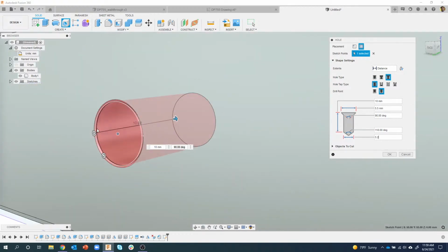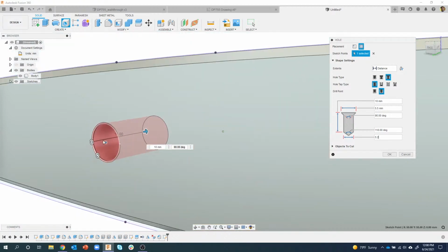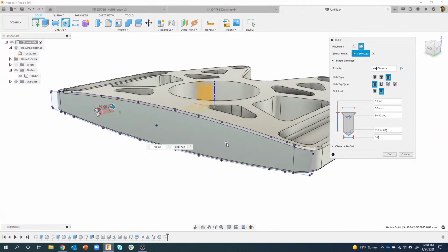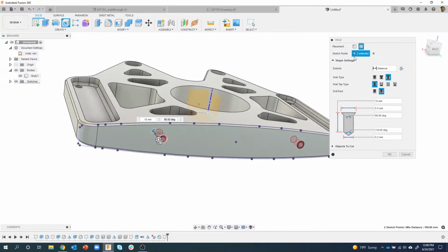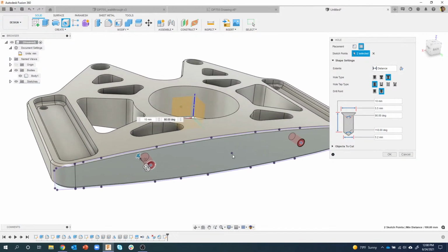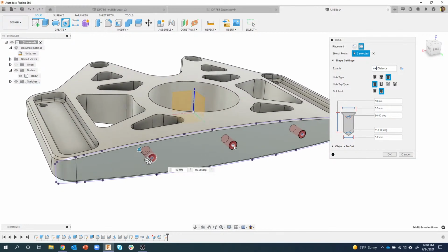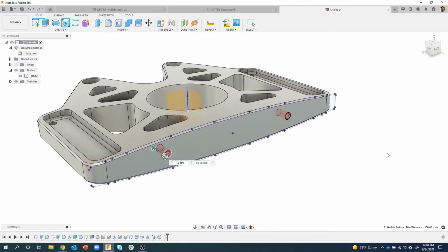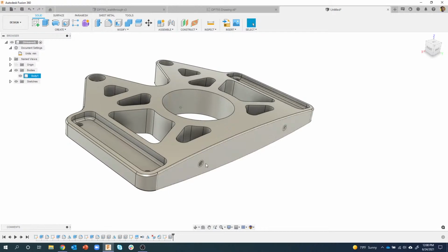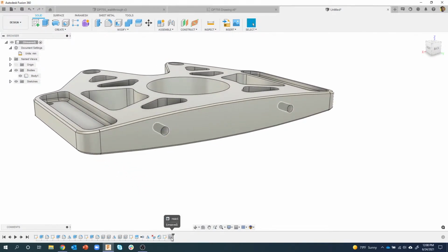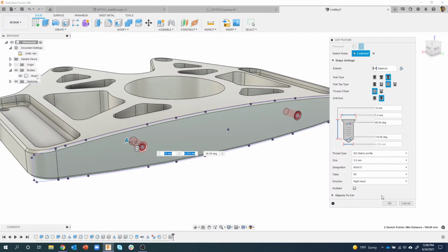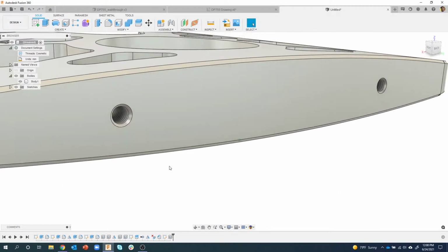So it's created that little countersink. We've got that drill point. We got it the right depth, and then I can just come over here and click that point right there. By doing this from sketch, I could just keep clicking as many points as I wanted to. I could even do that center point if I wanted to. We'll say OK. Okay, and I could come in here and say, obviously, we want that to be tapped or whatever. So now they're tapped holes.